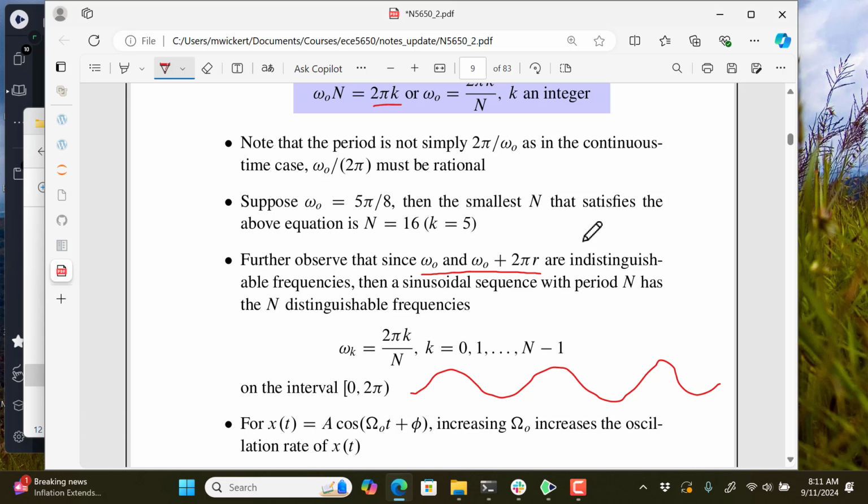So you'd be taking every other sample. Then you could increase that by 3. And then finally, you could go all the way up to the limit where you're striding the whole length, and so you're just taking the same value each time, and that would be like DC. You'd be taking the same value, putting out a constant, or in between, you'd be putting out all these other intermediate frequencies that are related based on the fundamental period, or the length, in this case, of the sequence.